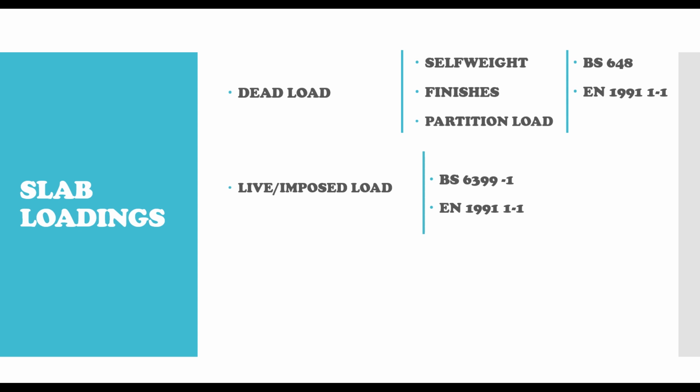Then the last type of load, which is not really common in buildings but is important, especially when the building is of a particular height, is the dynamic load. And the dynamic load that I'm referring to in this video is actually the wind load. The wind load can be analyzed by determining the static equivalent.